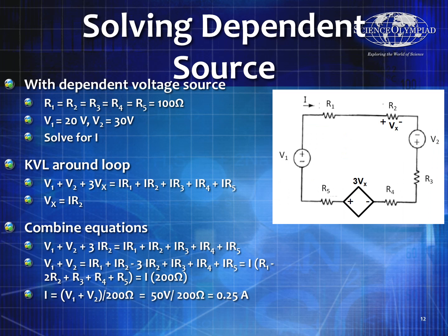In this particular case, of course I'm going to do a KVL. When I see I only have a single loop, I'll almost always do a KVL, and you'll notice that's actually going to give me just one real variable. And so I can really quickly determine, using Ohm's law and a single KVL, exactly what Vx should be.